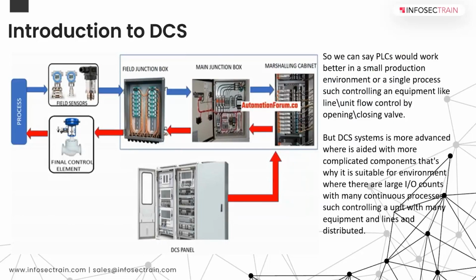So here we are: DCS, distributed control system, the darling of everyone. So what is a DCS and how does it operate? In a DCS, the total process is divided into a certain number of subsystems, and each subsystem is controlled by its own controller. We can describe a DCS as a large process controlled by a number of controllers, each controlling its own subsystem.